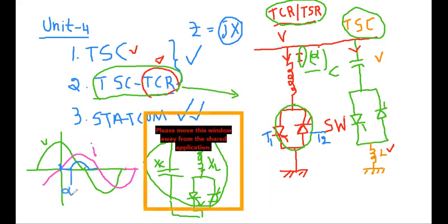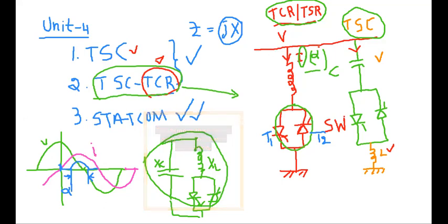So this is called a delay angle. Then this is the conduction angle. Okay, so that is reduced. Previously it was pi, now it is reduced to this one. That means we don't get the full current, only a partial or small value of the current here.